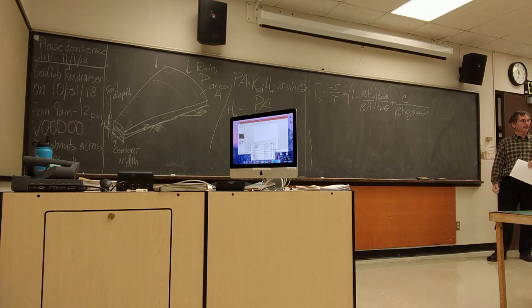But I've also never lived in a place that was on a slope of something really steep and wet, either. Something to think about. Remember Oso? Big landslide, killed a bunch of people in Washington. They said nobody could have foreseen this. That's crap. A colleague of mine did the numbers. He ran 2 scenarios. In the default scenario, he came up with a factor of safety of 1.2. And then he said, well, let me be a little more conservative and run a more dangerous number. He came up with 0.9. And that supposedly is nobody could have seen it coming.